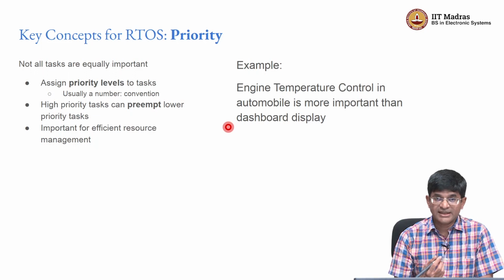And the second thing that can come up over there is the notion of so-called preemption. In other words, you could have tasks that, once they start, take a long time to run. And by long, we might even be talking just about milliseconds, right? It might be that if a task takes, let's say, 50 milliseconds to complete, for a human being that's nothing, for a computer that's ages. It might be that if I have not responded to a braking request within 50 milliseconds, I actually have trouble with the system, right?